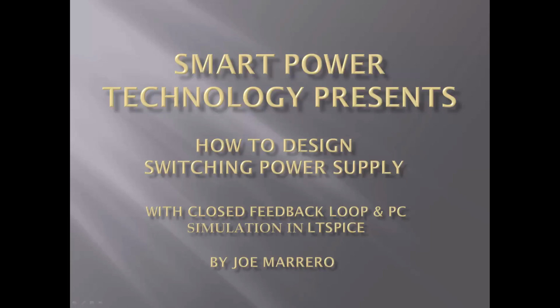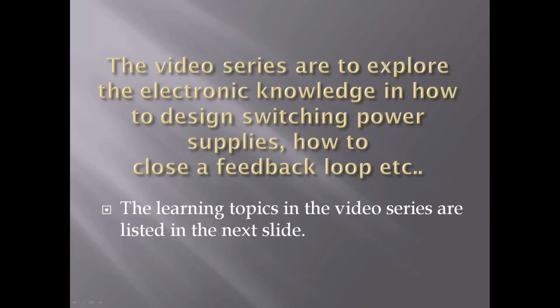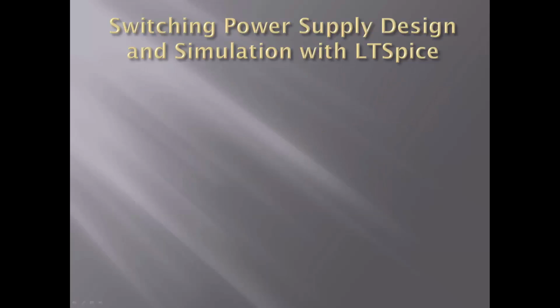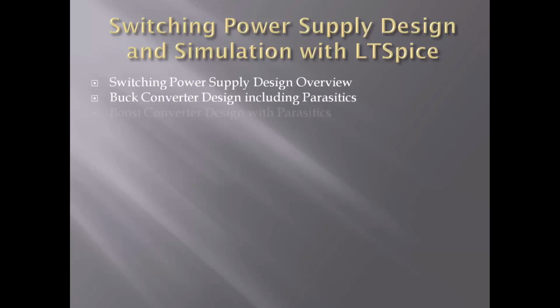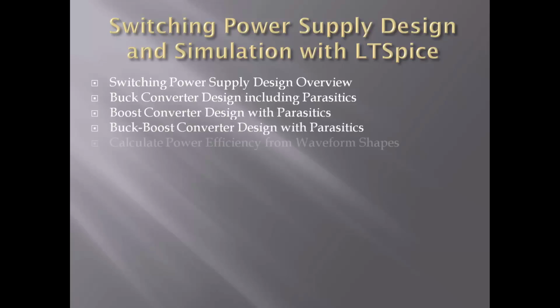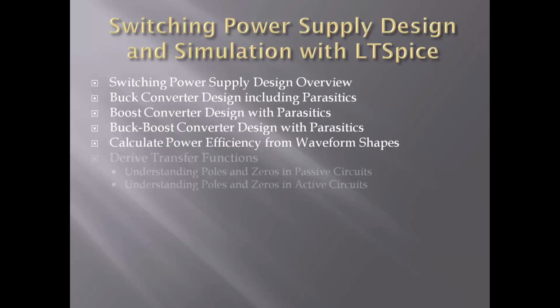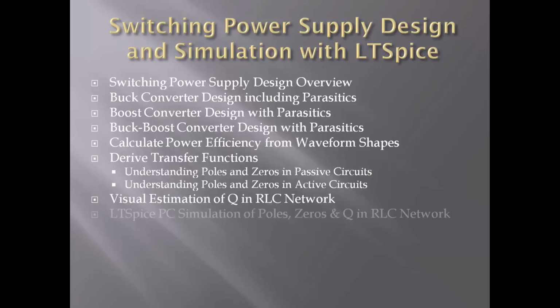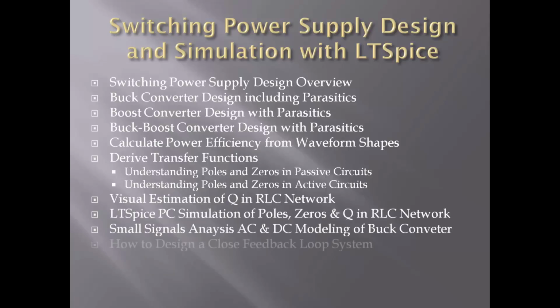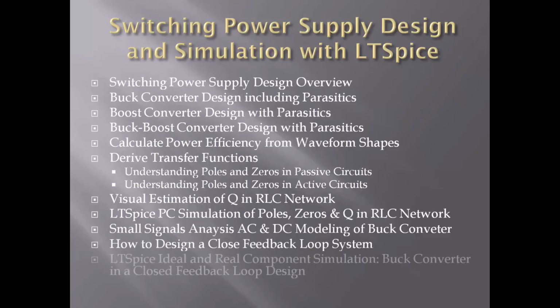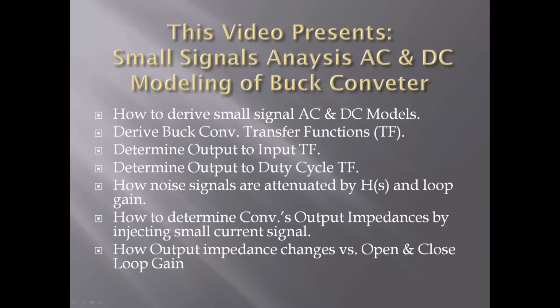Okay, how do we now find an AC model for this and start to close the loop? Because I want to do an example all the way through where we have a buck converter in continuous conduction mode, which means, again, the inductor current doesn't dry out at the end of the D prime cycle. And then put all together the circuits to see how you get the loop gain and how you get the transfer function from input to output, an AC transfer function over the whole loop gain.